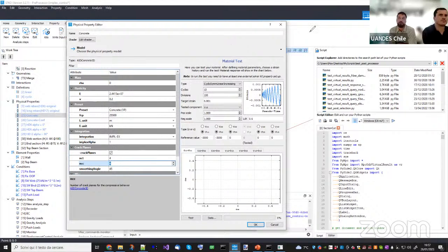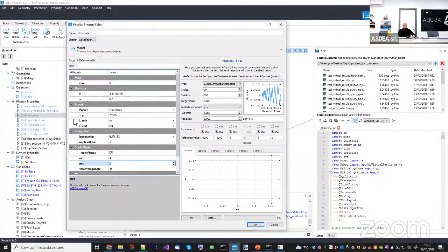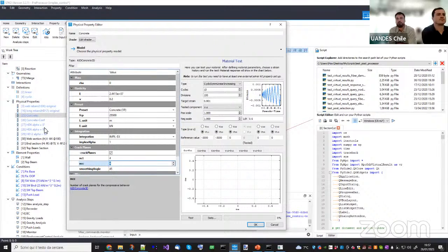But that should be implemented in the specific model. Actually, now you gave me an idea, because the next step that I wanted to do in one of these webinars is to put the fracture in steel, but yes, then you don't have regularization. Now, many people do not consider it for one reason, basically, because when you break the steel in a reinforced concrete structure, you're basically at the very end of the analysis. So whether you regularize it or not is, in some cases, not important, but in general, yes, you need it. So it should be done.